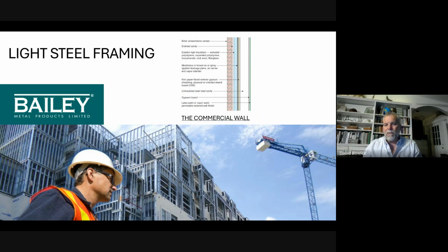Steel studs can be used in a load-bearing or non-load-bearing application. So this particular diagram, these steel studs are load-bearing. And so they would be a slightly heavier gauge. If you walk on any construction site, you are going to see lots of non-load-bearing steel studs. They're very fine gauge. They're quite flimsy looking. But once they're built into a wall, they're much heavier and much more robust.